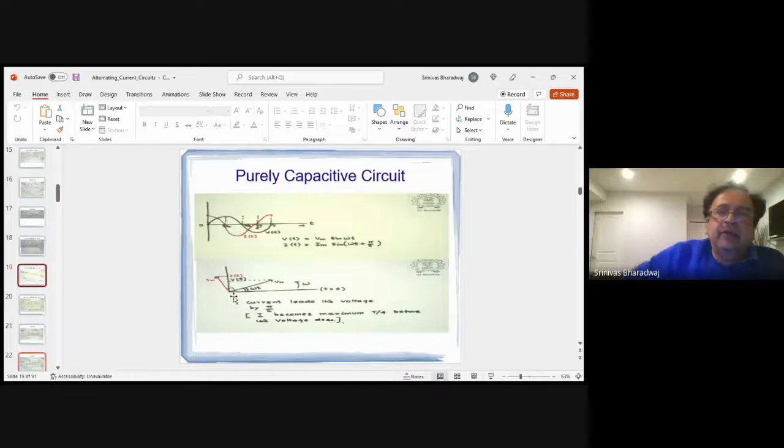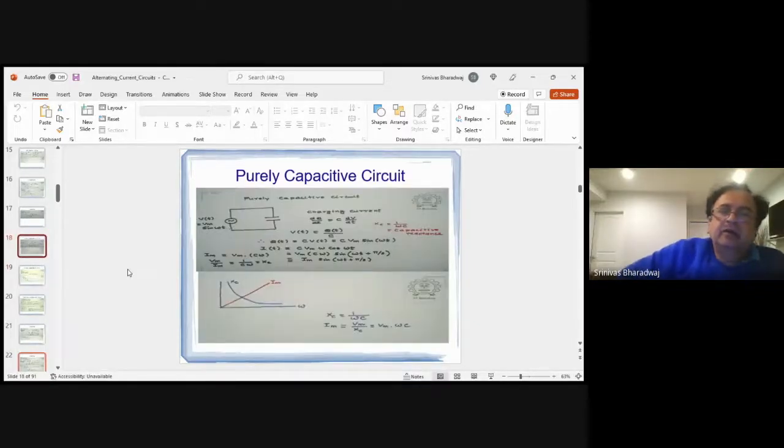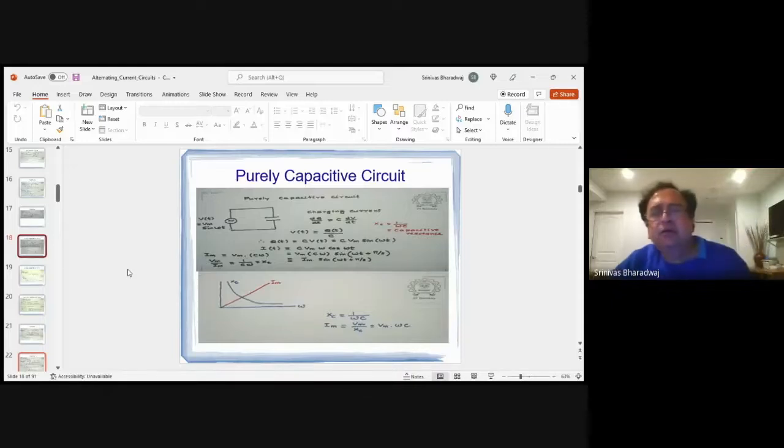So when we look at the impedance, you will have R plus j omega L, and in this case R minus j by omega C. j is just the square root of minus 1, the imaginary number like i. So if you had both a resistor and a capacitor, you will have R minus j by omega C, where 1 by omega C is the corresponding XC.